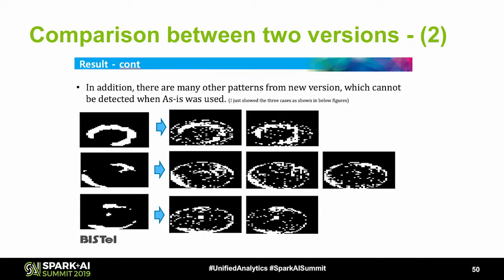However, in the new RMA, we can adjust the parameter easily so that we can detect more specific patterns by adjusting the parameter value C. As shown in the figure above, the white represents the defective chips, and the black background is the wafer map. Even for a small number of wafers, such as 2 or 3, clustering patterns can be found very well. So in this clustering, as you can see, the first cluster pattern is obtained by clustering just 2 wafer maps.